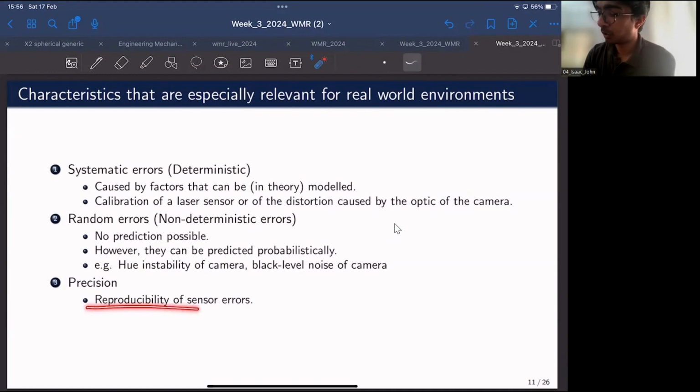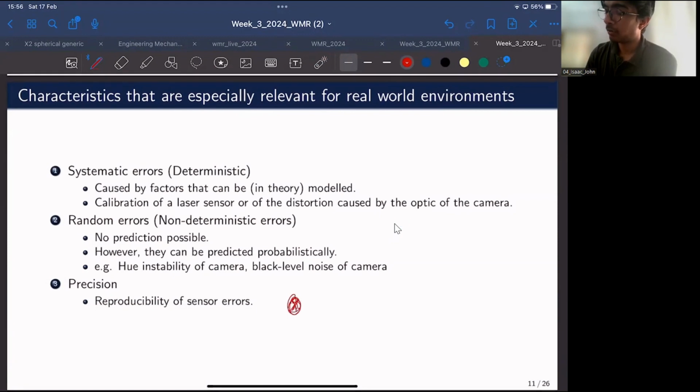For example, for the first measurement you get a reading at this coordinate, and for the second measurement you still get this coordinate. If all the time you are getting readings very close to this coordinate, you can call this a highly precise reading. But if the measurements are all over the place, then that becomes a reading of lower precision. So precision is repeatability. It's another word for repeatability.